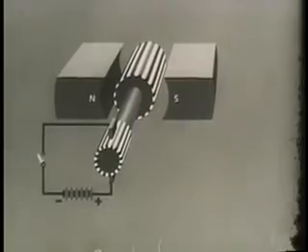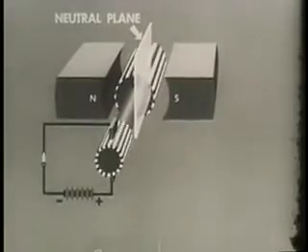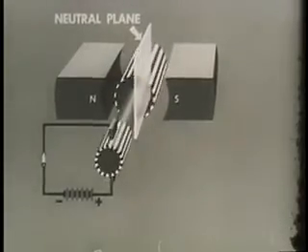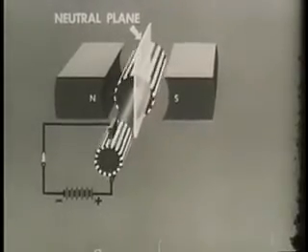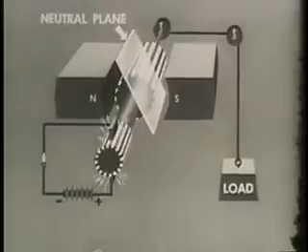Here in the motor, as in the DC generator, there is a neutral plane. The interaction of the conductor fields on the main field causes this neutral plane to shift and sparking to occur when a load is added.